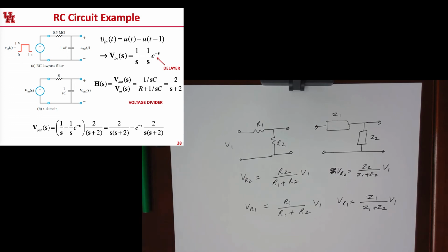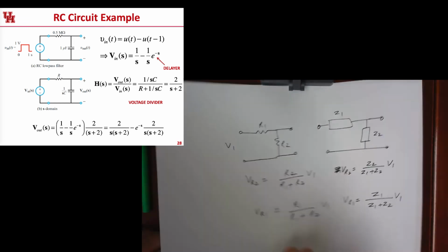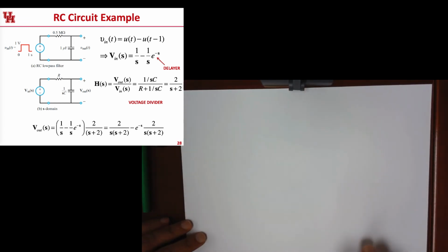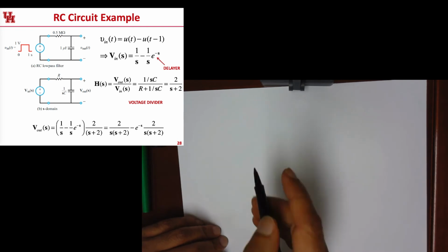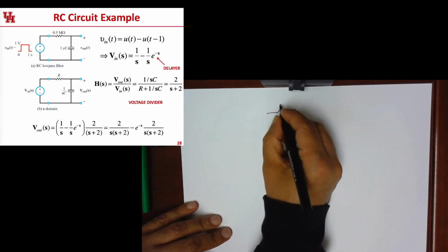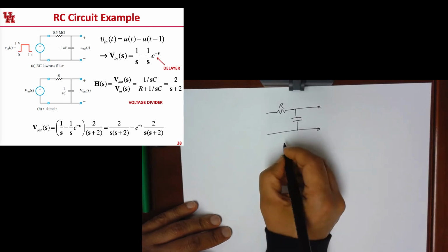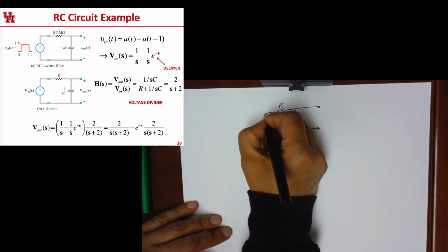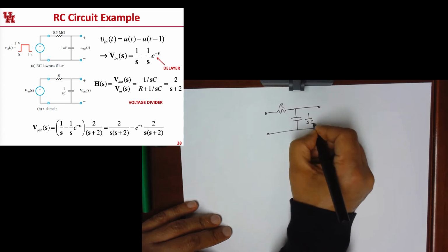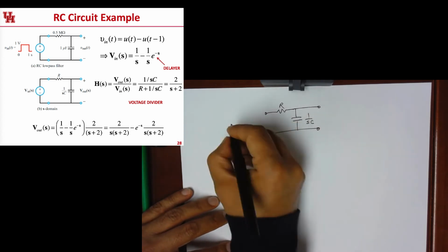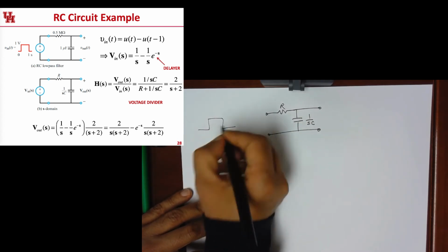So we can use this now to reapproach our RC circuit example, a good old circuit example that keeps coming back at us all the time. Okay, and so we got the RC circuit like that. So I can directly go at it in the Laplace domain. So I'm going to write this as 1 over SC, right? And my Vin was a pulse, right?